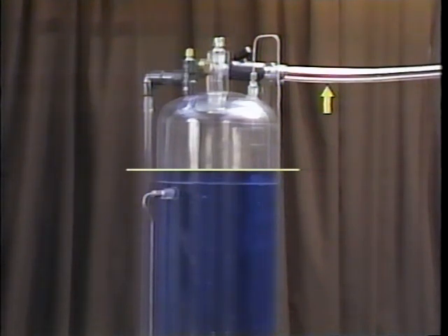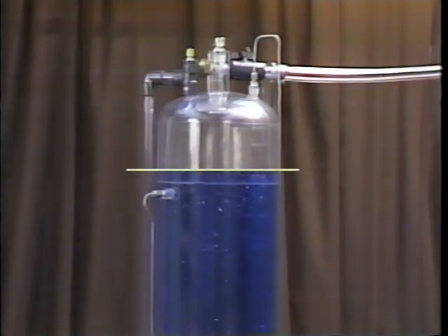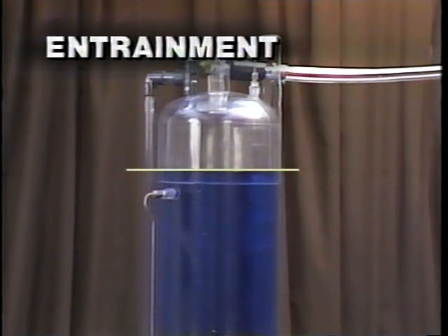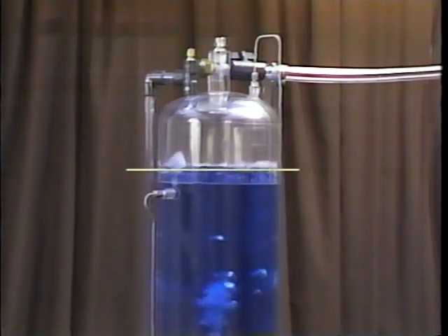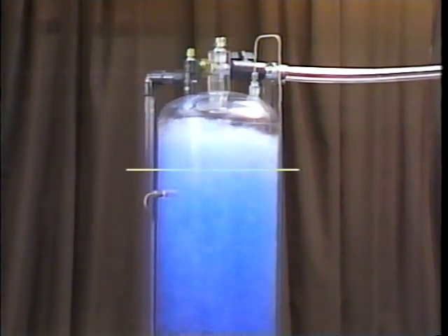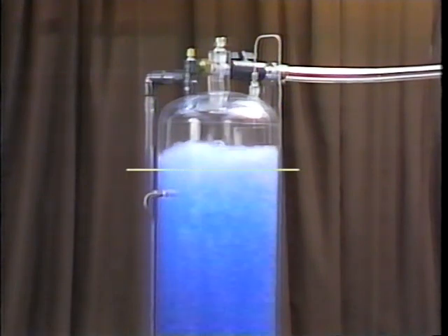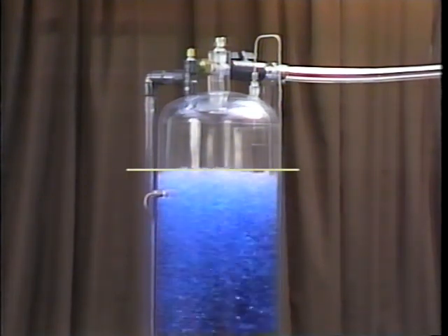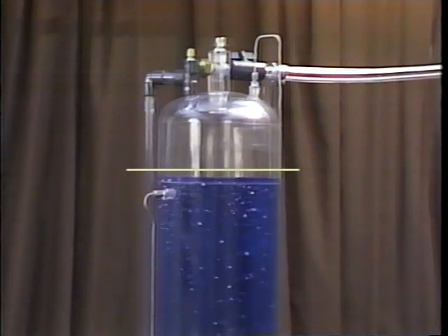Watch the vent nozzle at the top of the tank. Instead of venting only gas, a two-phase product will be vented, both liquid and gas. This is called entrainment. In time, enough two-phase product will be vented and the height of the liquid in the tank will drop down to a safe level. But in the meantime, a large amount of product is being lost to the atmosphere, creating a potentially serious safety problem.